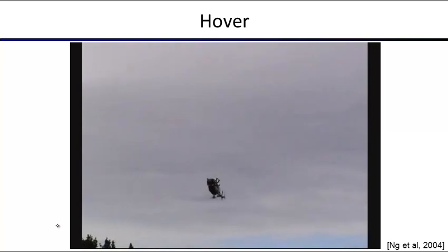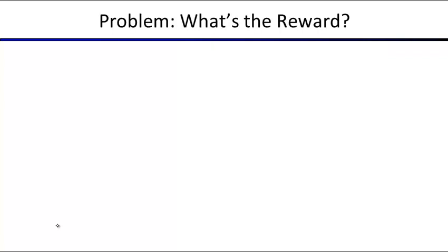as a side note, what's interesting about flying upside down, it's more effective because when you push air through your blades, you accelerate that air, and it's going at twice the speed below the blades compared to above the blades. Now that air is passing by the helicopter body and causing friction and dragging the helicopter body down. So it's nice if the body is above so that half the speed air is going over that body rather than when the body is below where you have double the speed of the air dragging over the helicopter. All right, so that's hover.